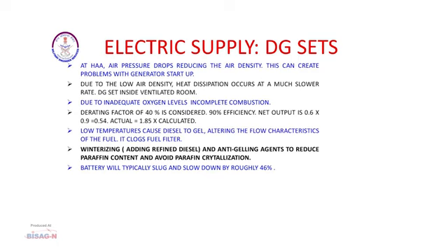But since the climate is very severe outside, usually a DG set room is made in which DG sets are stored inside. These buildings are regular buildings which are not so ventilated, which further results in heating of the engine of the DG set. So it is a duty of the executive to ensure that we provide iron grills only, which are properly ventilated. Due to inadequate oxygen levels, incomplete combustion of fuel happens, hence the performance is not satisfactory.